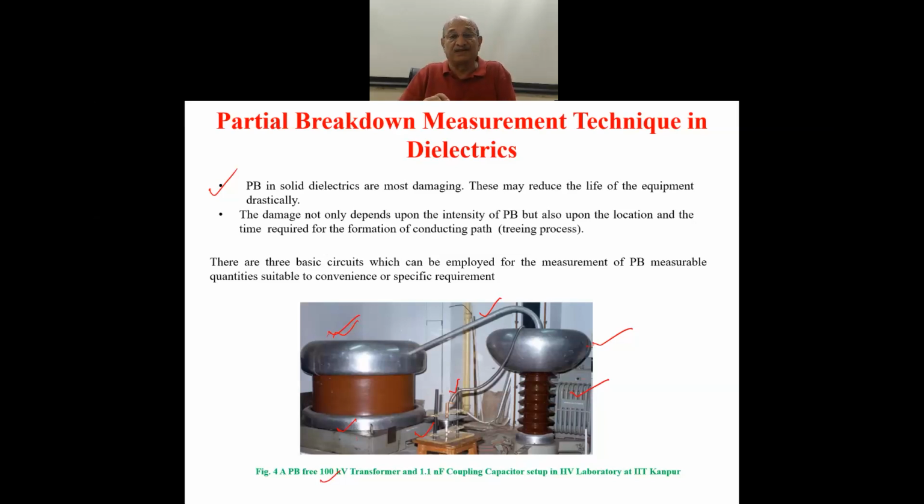This is also a standard capacitor, and it is designed in such a way that it has very low losses. It is not made of gas or vacuum, but of oil and solid dielectrics, but it incurs very low real power loss. This is the coupling capacitor. A coupling capacitor, you can have this, but in case of a standard capacitor, it should be loss free.